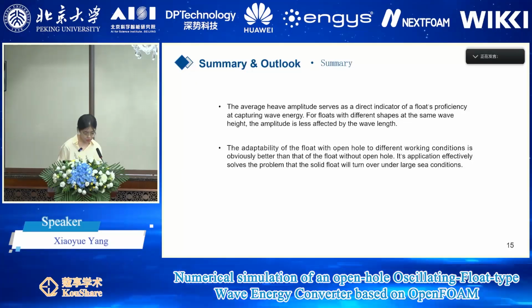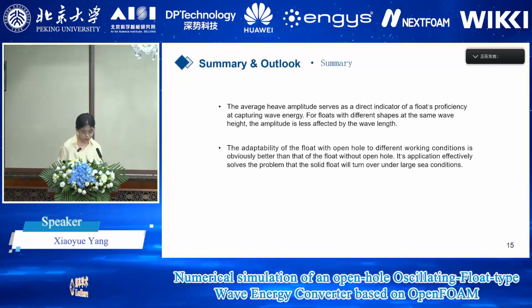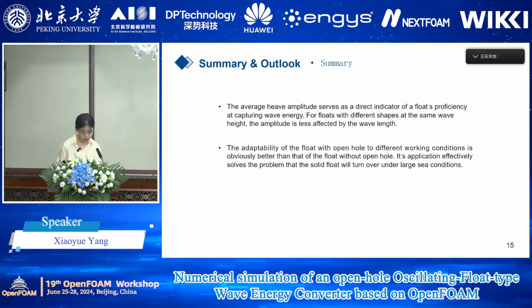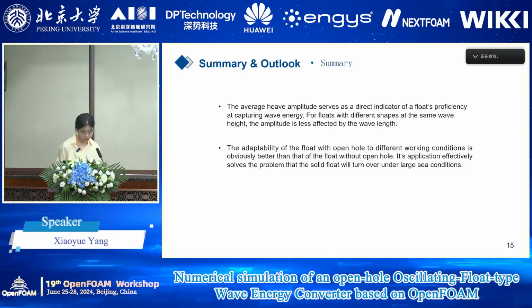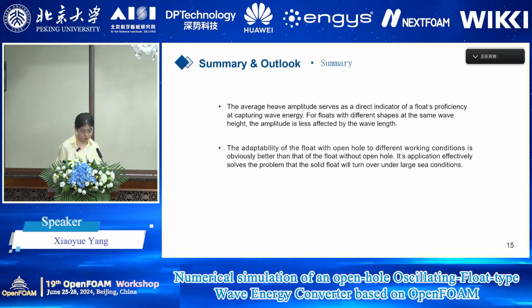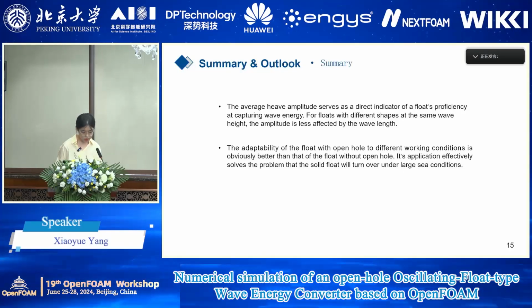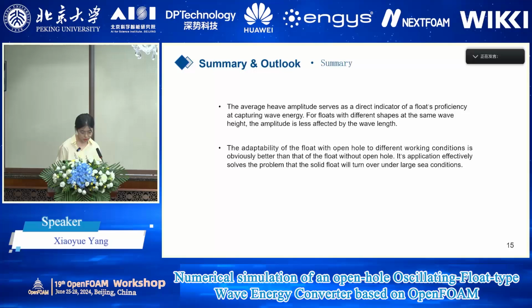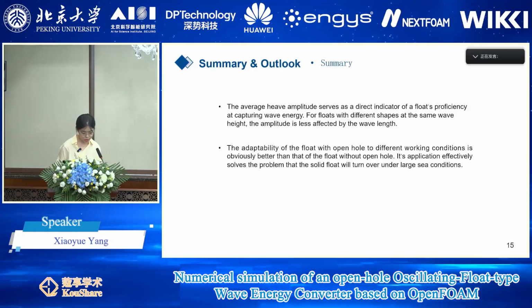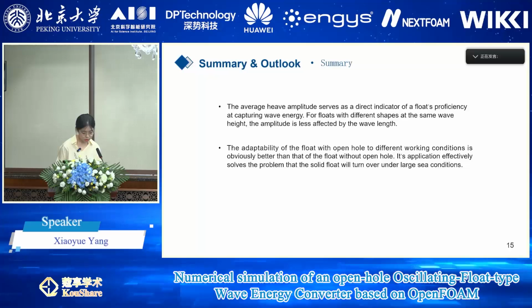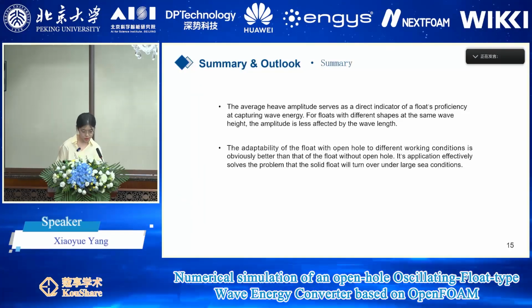The adaptability of the float with open holes to different working conditions is obviously better than that of the float without open holes. Its application effectively solves the problem that the solid float will turn over under large wave height conditions.